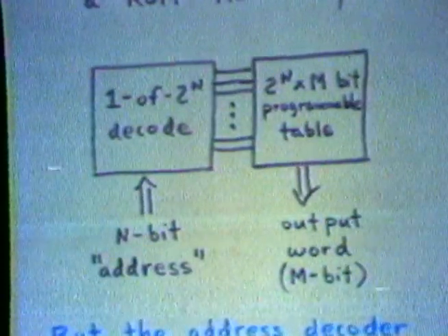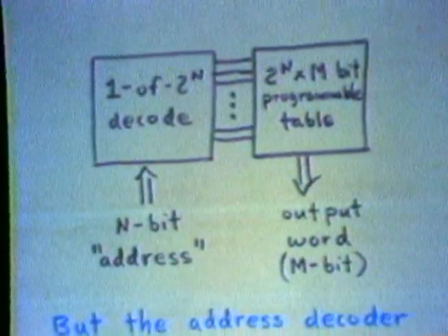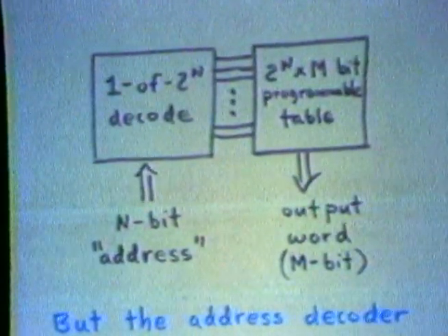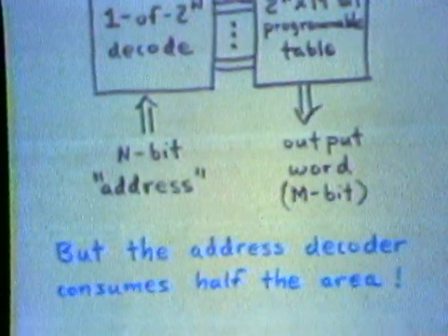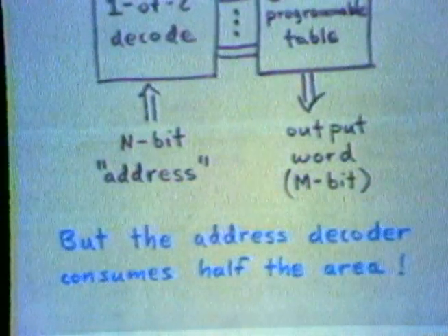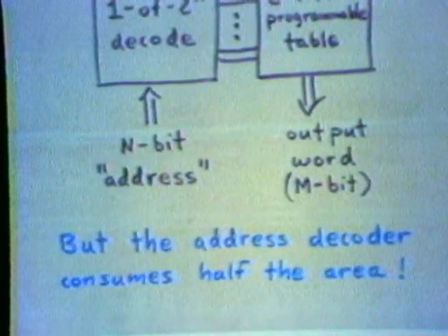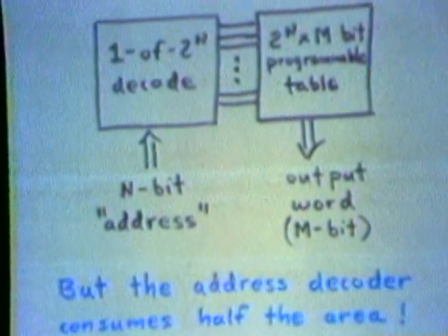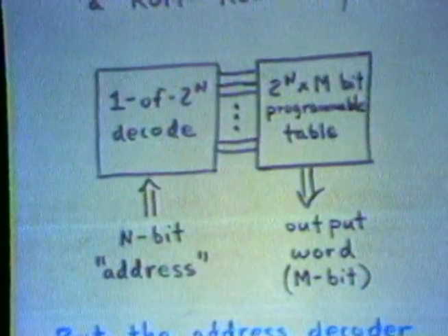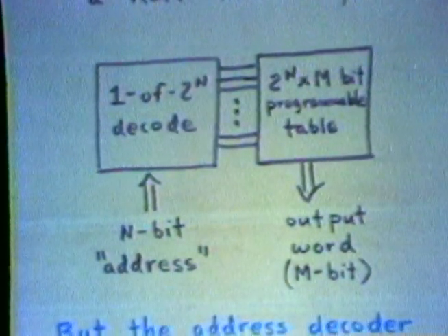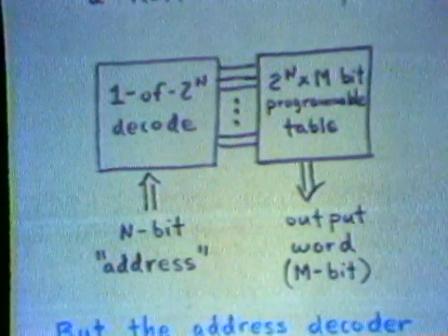And of course the question was asked, how does a PLA compare to a read-only memory for implementing logic? And it depends on how you think about comparing it. If you build a fully decoded PLA, which is this ROM, then it will in fact implement any n-input logic function, and by increasing the word width, as many n-input logic functions as you like. If you build a PLA, there's a good chance you can get away with fewer product terms, that is, less height in the structure. But if you go to change the program and suddenly find that you need more product terms than you designed in, you may wish you had used a ROM. Depends on how easy it is to change your design.